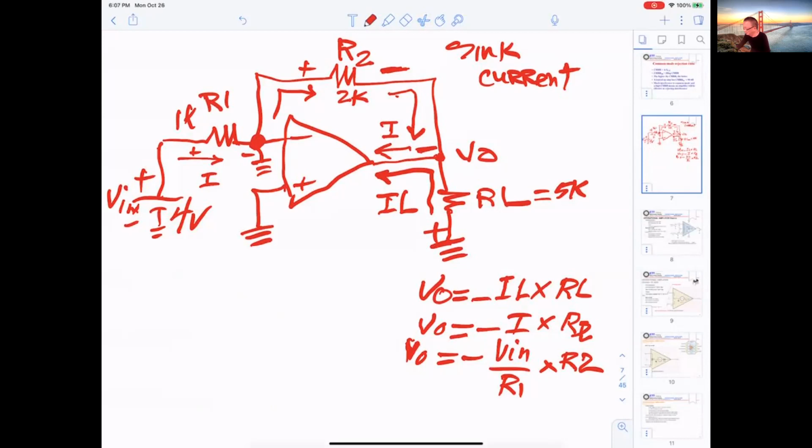So now you get the gain A. However, in this case they call it ACL. CL means closed loop gain. When you connect a resistor to the circuitry, the gain is no more open loop gain. Now it will be closed loop gain. So ACL equals V out divided by VE.